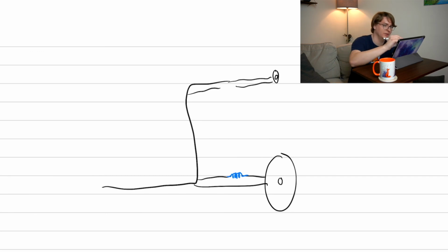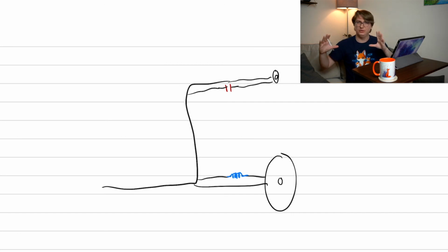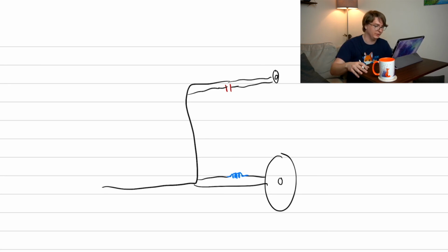Now let's think about the tweeter. Tweeters like high frequencies. It likes quick changes, but it doesn't really want the low frequencies. It wants to pass those off to the subwoofer. So what would work well? Well, a capacitor loves switching current really quickly. It loves high frequencies. Remember, its impedance goes as 1 over 2 pi f C. If it has low frequencies, it causes charges to build up for a long time. It doesn't like that. It likes quick switches, so it always has room for charges to get off. So I would put a capacitor at the top, and that would filter out low frequencies.